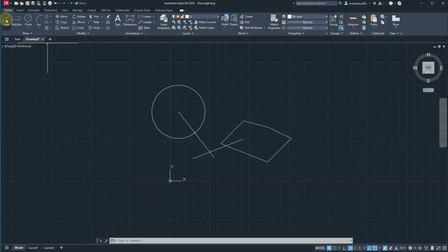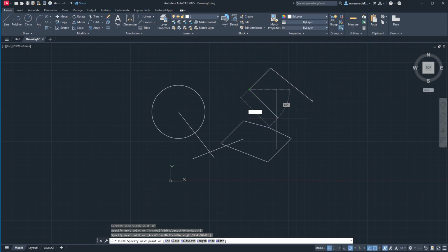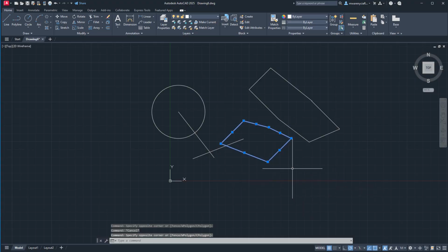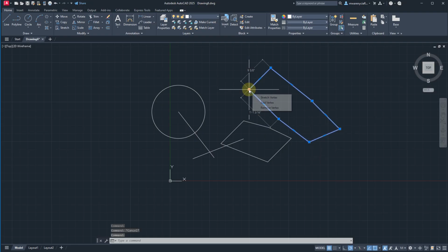So we've used the line tool now. We've placed a couple lines. The other option is going to be the Polyline Tool. What this does is create a joined set of lines. I have this shape right here. Each of these is an individual line. If I select them, you can see that the middle box is a square just like the edges are. This, on the other hand, is a joined set of lines. The endpoints are going to be squares, but the midpoints are going to be these little thin rectangles.